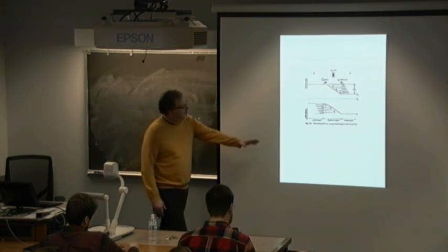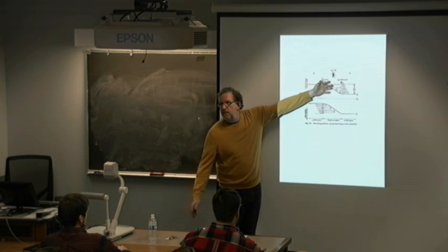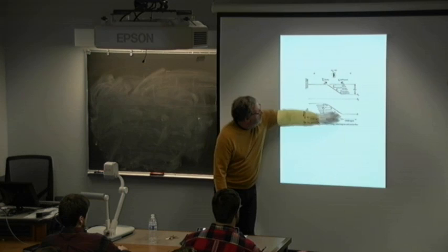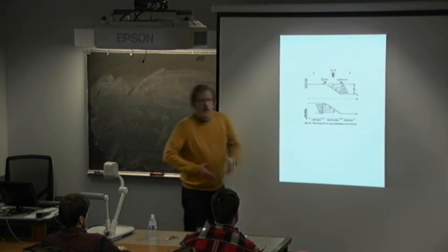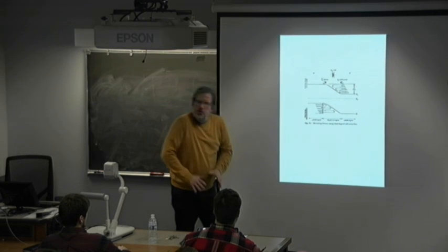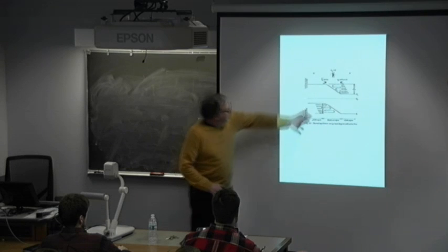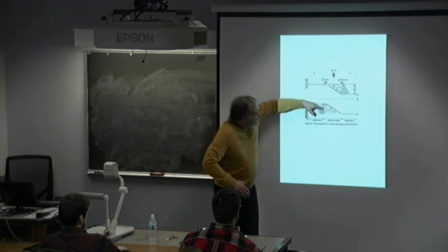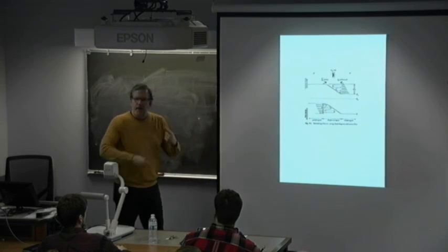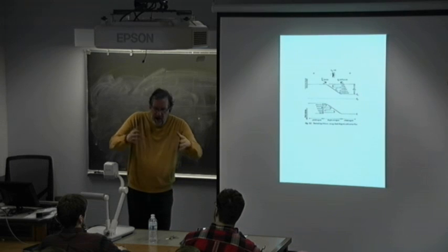And the holes, of course, you have to stand on your head for this, but the holes follow the same argument. They're basically air bubbles, and they're trying to come up. So think of the hole as like a beach ball. You're at the swimming pool and you're trying to push a beach ball below the surface. It takes energy, so the holes are gaining energy. They're going this way, so everything's inverted. It's not the presence of water; it's the presence of lack of water. It's the air inside the beach ball.